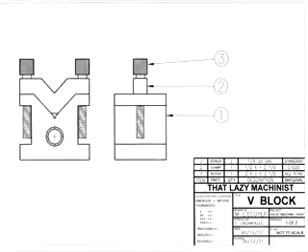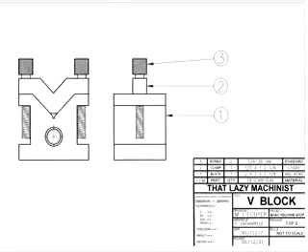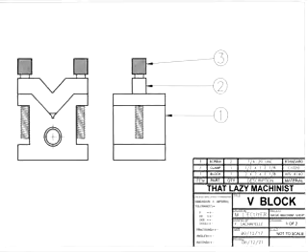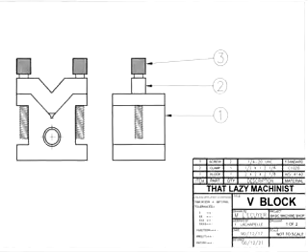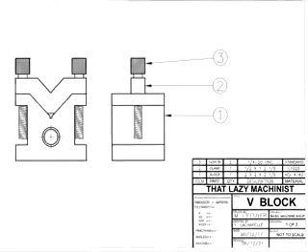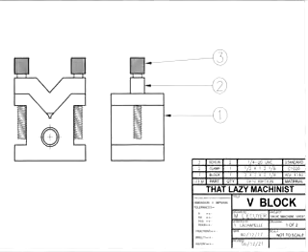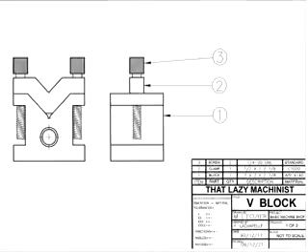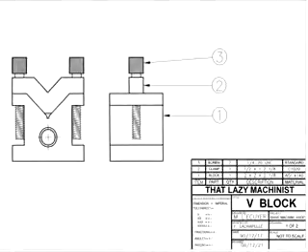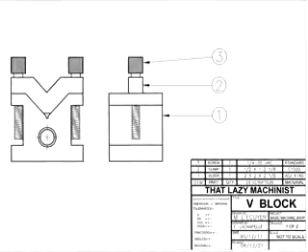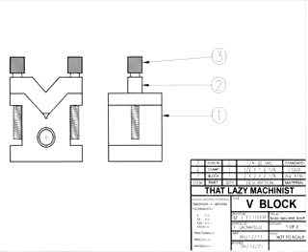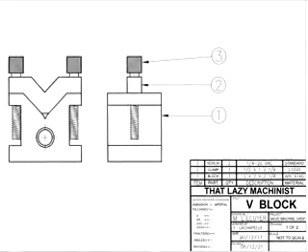Reference dimensions exist for two reasons. The first is a dimension on an assembly drawing. And as I've explained earlier, since assembly drawings show assemblies, the tolerance of each part cannot be calculated, so an overall dimension on an assembly drawing cannot be used to manufacture the part.